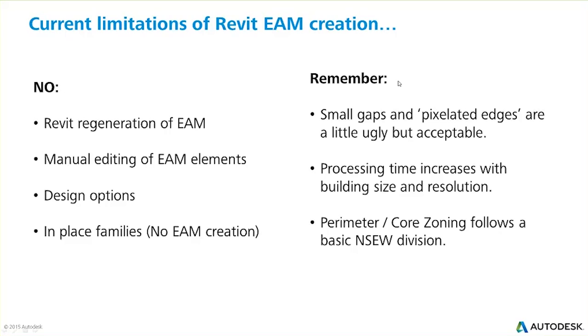And one of the things I could share with you now, if it appears for me, there we go, is that most of you will know we're now on a twice-a-year release schedule. If you're on subscription, you'll get what we call R2, and that feature is going to be added, or has been added, to Revit 2016 R2. I know most people upgrade around that time anyway, so if you're using that, you'll get the new, more advanced automatic thermal zoning, which just adds more accuracy at that very early conceptual stage. It's a really nice feature that we've taken from Vasari. We're doing it in a slightly different way, but it effectively does the same thing. And what's interesting is it's not only applied to the conceptual mass element, it works for both.